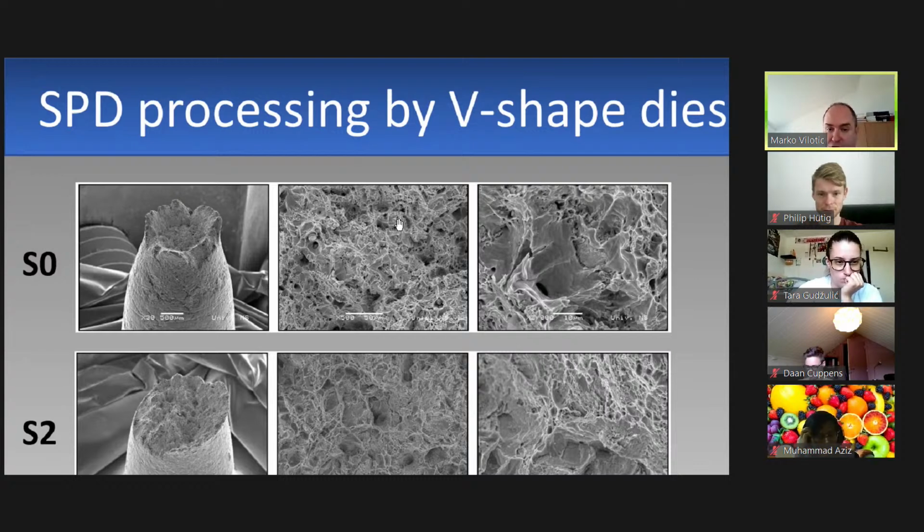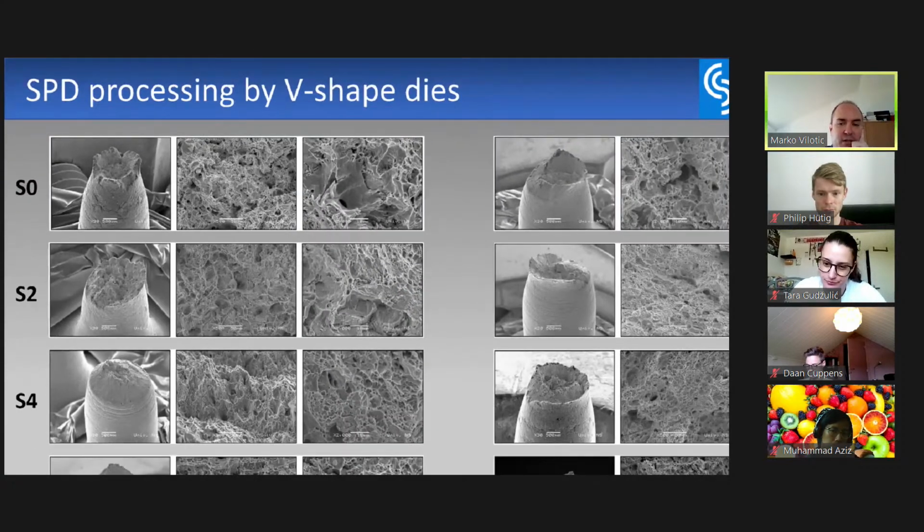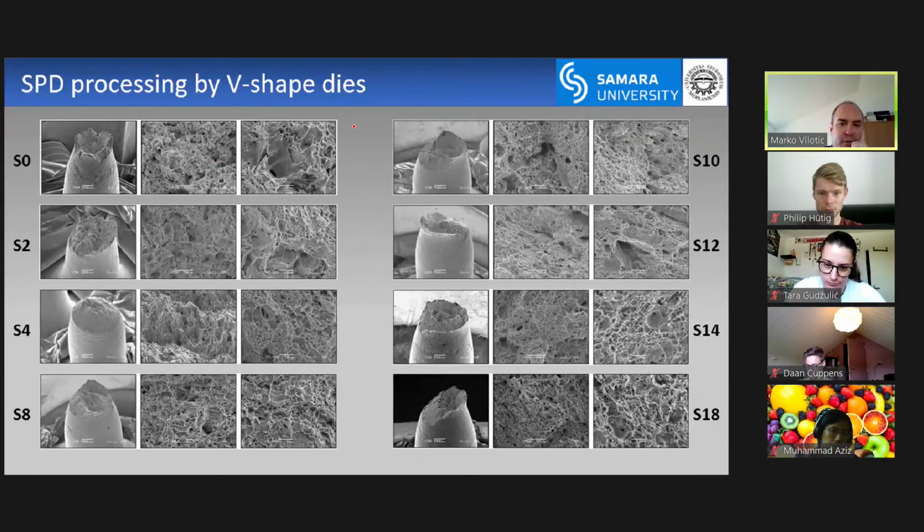So it's not a brittle fracture, which is very important, because in some applications this material can be dangerous because of brittle fracture. And they call this shape, if I'm correct, cup and cone. So something like this, if I remember correctly, sorry.